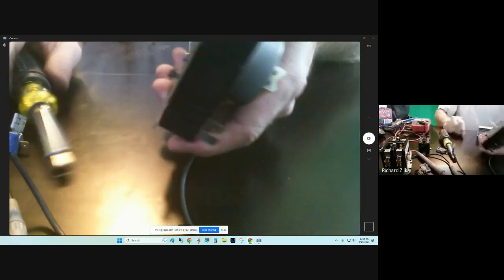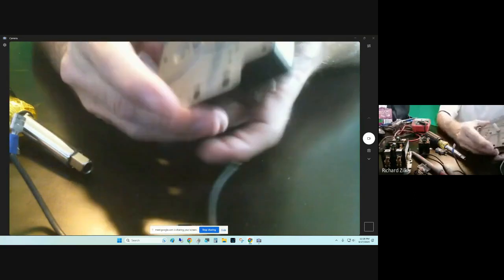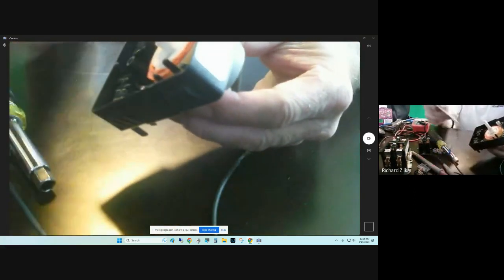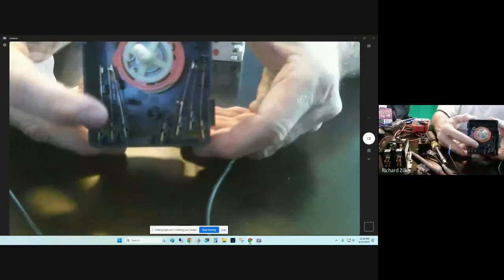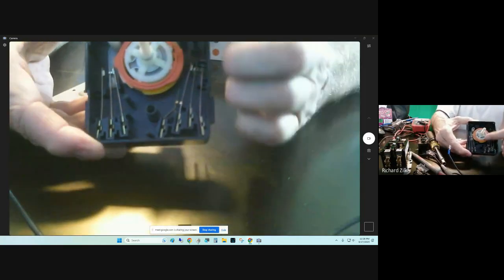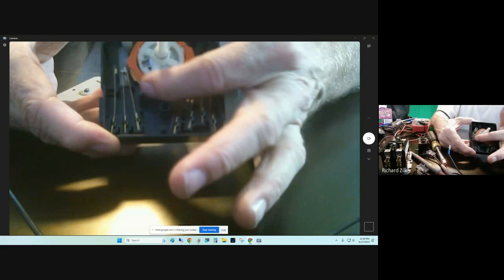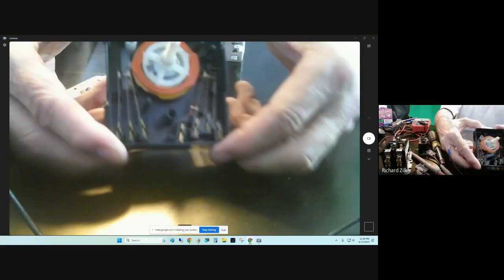I'm taking off the screws in the front cover here. And carefully, you can open these timers up, and carefully, we pulled off the top. Now we have all these different switches inside that are either open or closed. And we call this part of the timer the cam. And you could see that they have different portions that are cut and raised on the timer.